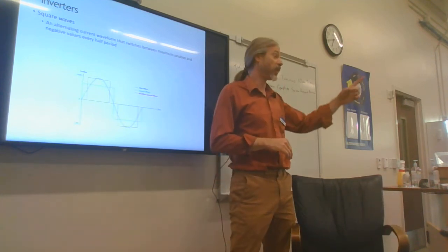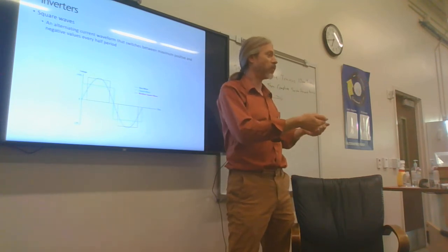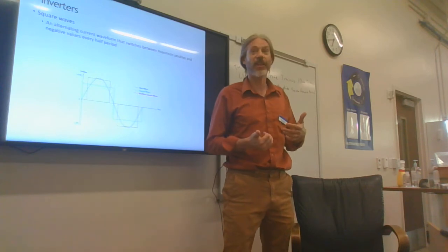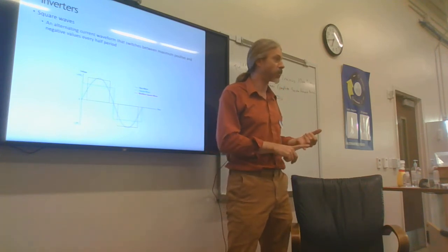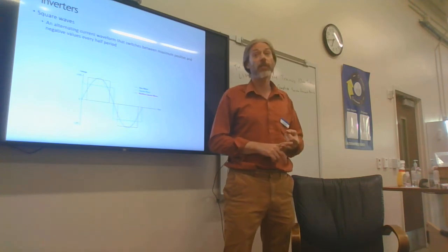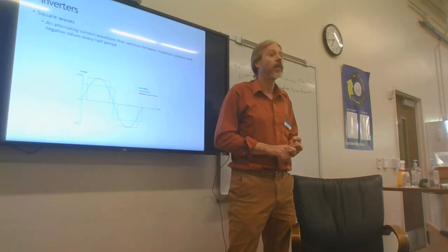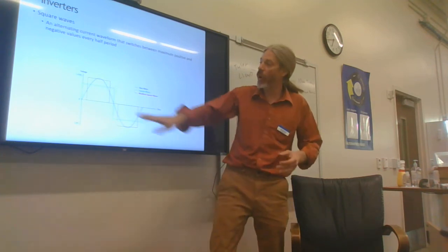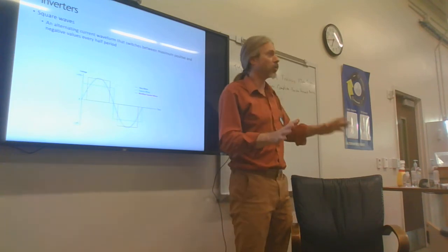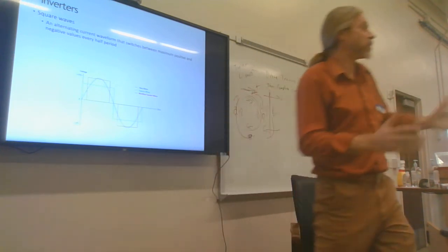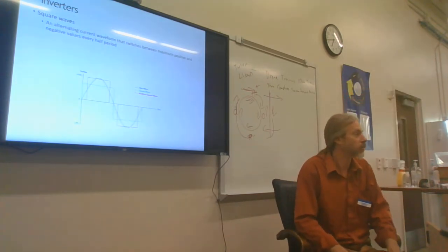be. If we go get a cheap little $200 inverter that just hooks up to a 12-volt battery and you look at the efficiency of it, it's probably going to be like 85% efficient. It's not going to put out a true sine wave. Might not even be a modified square wave. Might just be square wave, and that's it. Why is it so inefficient? Because all of this extra energy that is not used by a normal standard appliance is just wasted. It's dissipated as heat, and therefore it is highly inefficient.